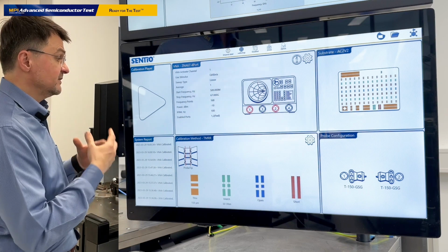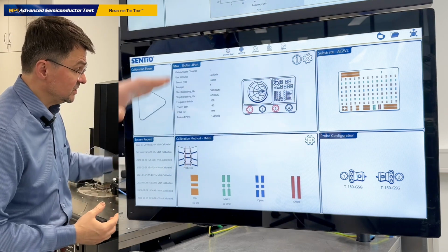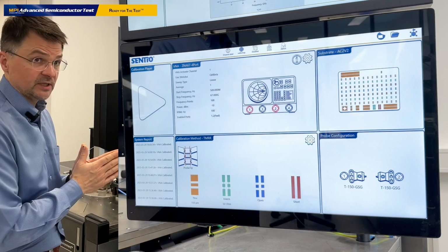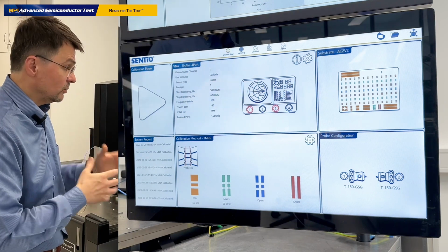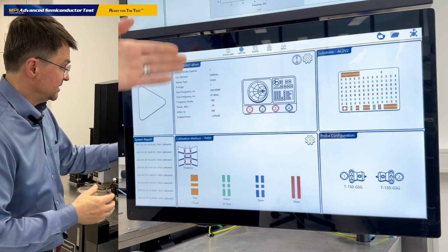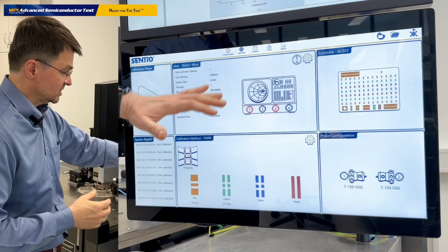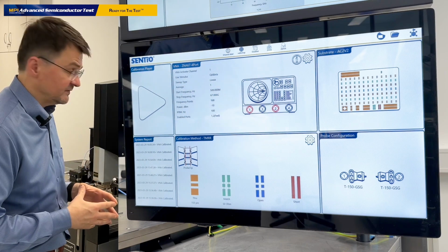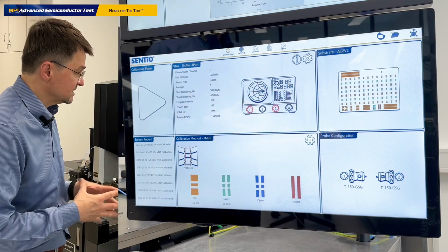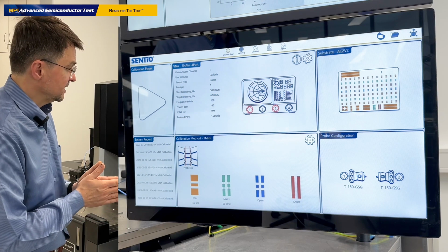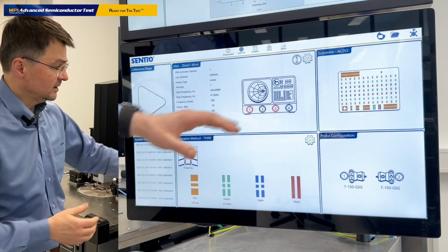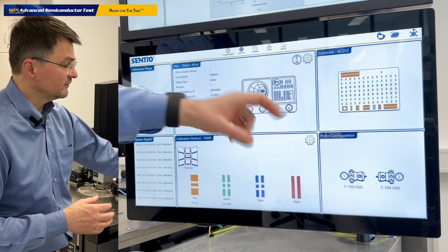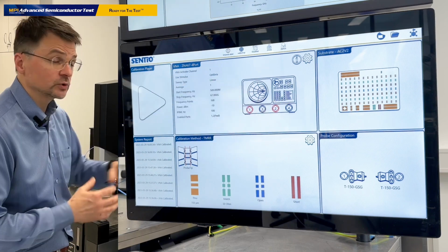It means that you need to have access to the network analyzer, and this is the widget which gives us the quick access to the settings of the network analyzer and also displays what the current settings are from the list. We see that we currently have just a sweep starting from 500 megahertz up to 67 gigahertz. This is the ZNA 67 gigahertz 4-port network analyzer from Rohde & Schwarz, and it's configured for the 2-port measurements, while this is the 4-port device. It's configured for the 2-port measurements, and port 1 and port 2 are active.